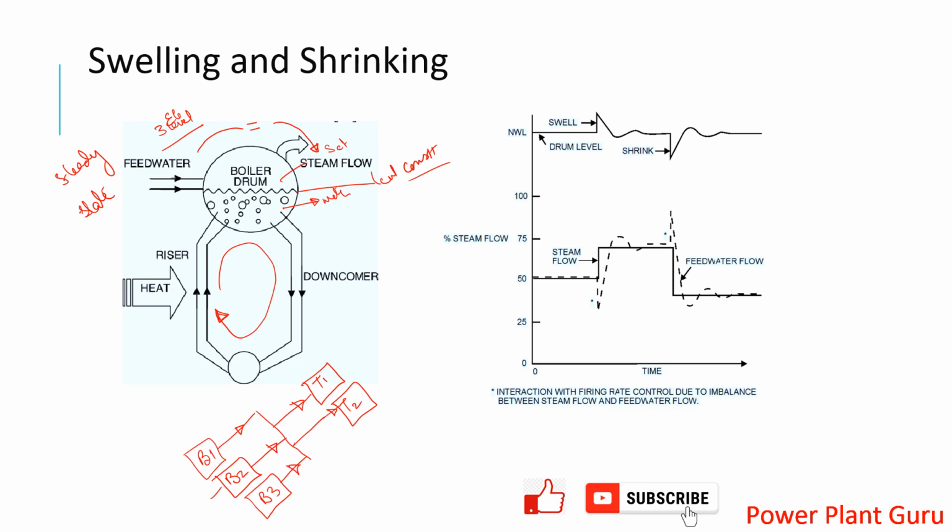Now this B2, what will happen if this one boiler trips? This trip means there will not be any steam flow from this. So this supply cutoff will definitely reduce the pressure in this entire region, because the turbine is still consuming, and here is the one steam source which is cut off. So boiler 1 and boiler 3 will try to push steam into this void or low pressure condition.